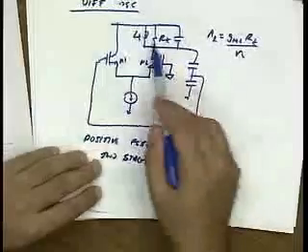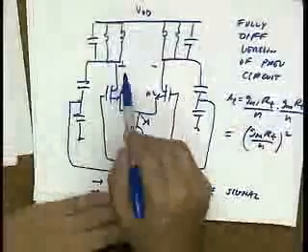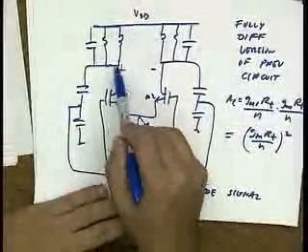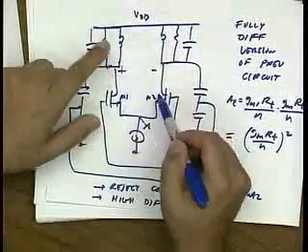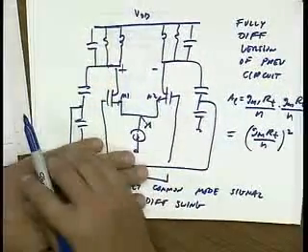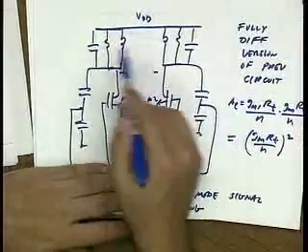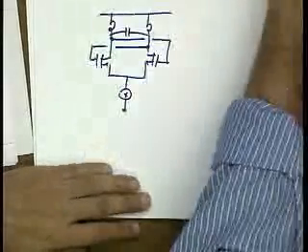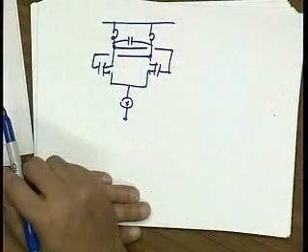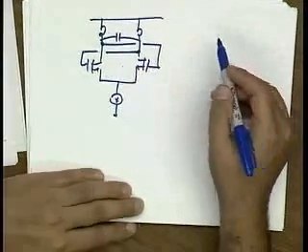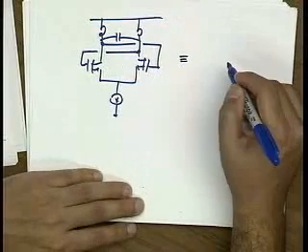So here this is a single-ended version. Now I have 2 caps, and because this is a differential signal, I can actually make my cap smaller by connecting it across here, right? Because these voltages are out of phase. So the cap looks twice as big. So instead of putting 2 caps here, I just put 1 cap across here, and it resonates at the right frequency. Okay. Now most people draw this circuit in a slightly different way.